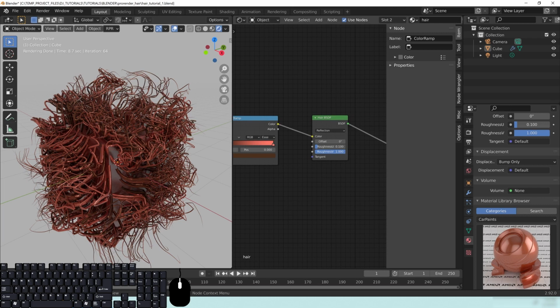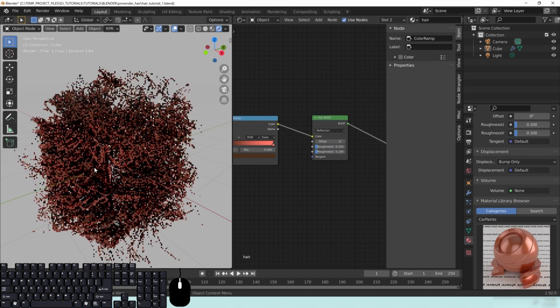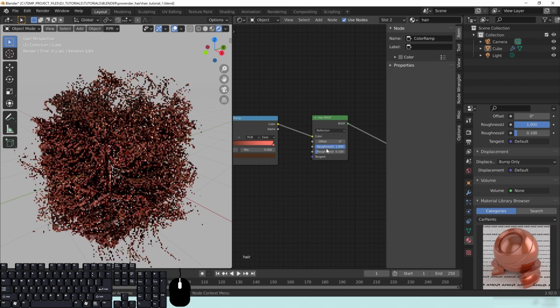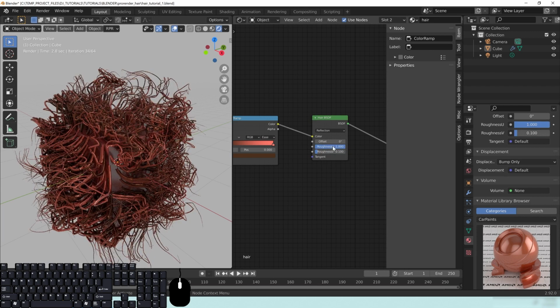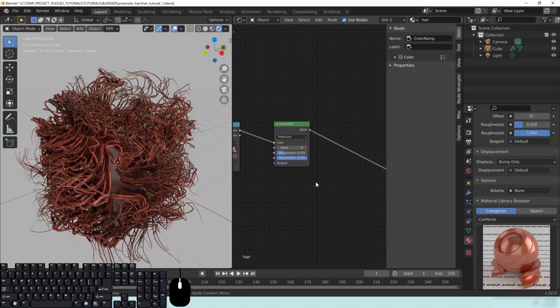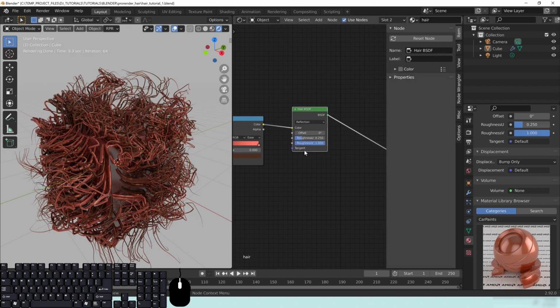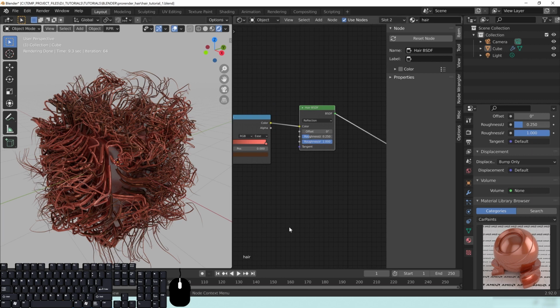And from here, you can also play around a little bit more with these roughness settings. So basically, the way that this is done is that the roughness is set in two different directions, the U and the V, and you can play around with these to get it how you'd like it. I've noticed that setting the roughness rather high and keeping this kind of more at the default with the 0.25 here is a little bit more natural when we start adding the other part of this hair texture. I would say this is an area that you should really play with so that you can see what you like and just see how everything kind of works.